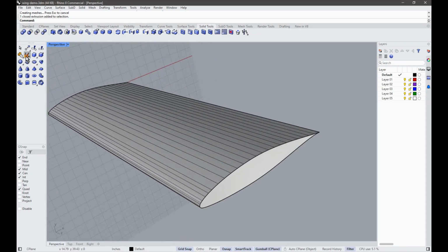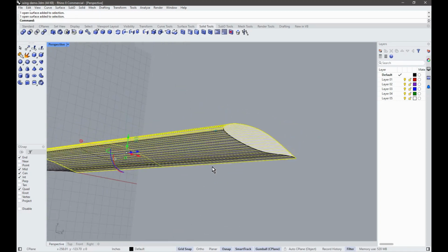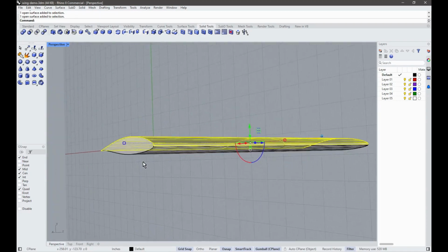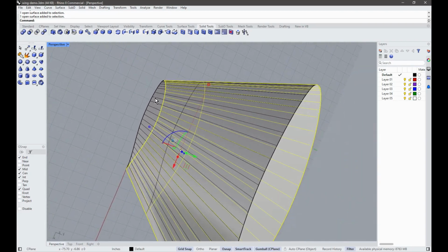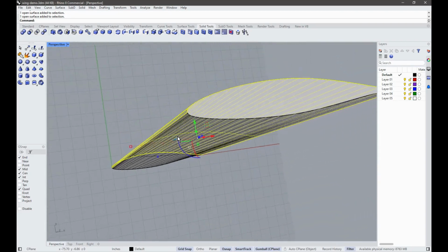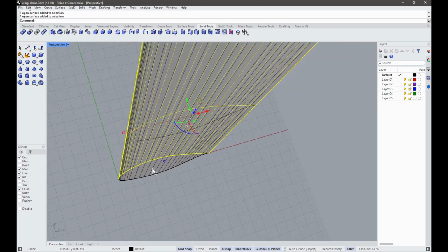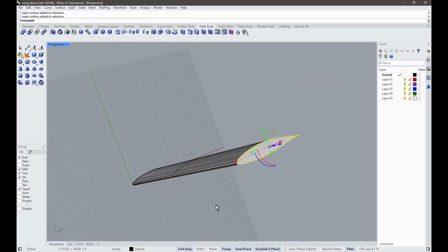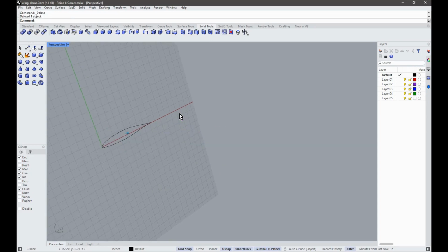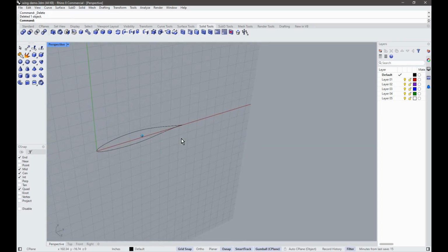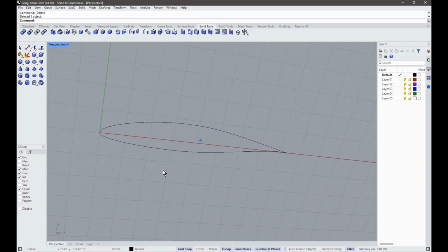You can also, if you want to break it apart, do an explode, which is literally just explode. Click on that, and now the ends and the top are different. But because we made the sketch watertight, let's see here. Actually, that didn't make any difference there. So with the explode, it made an upper surface, a lower surface, and two ends. We'll undo that, and we'll just delete this. So the next thing we're getting into is scale.